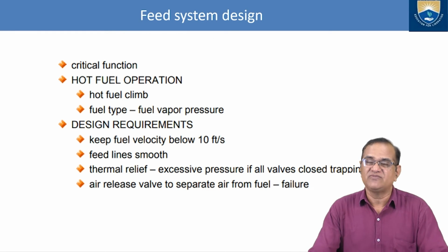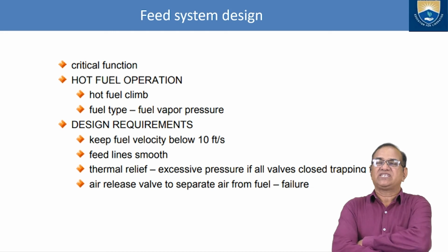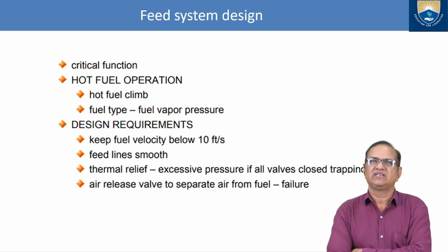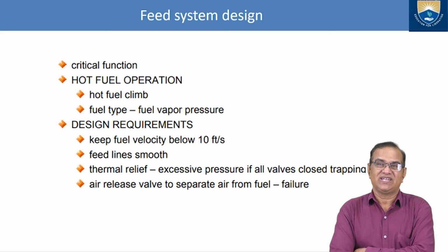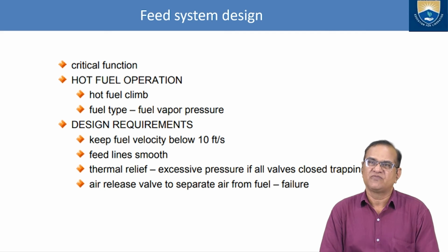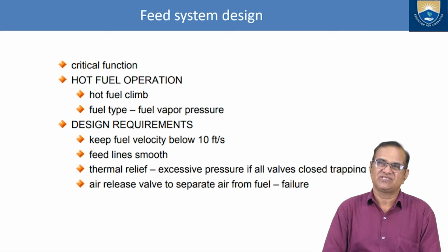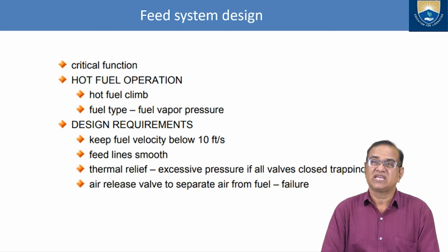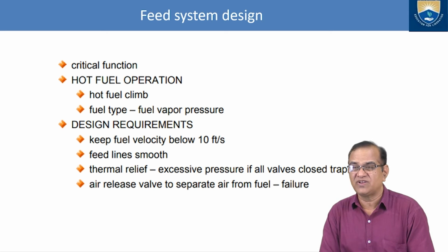Feed system design, if you talk, it is a very critical system to design. Hot fuel operations. Sometimes we need the hot fuel, especially in the cold weather. We have to heat the fuel. Fuel types, fuel vapor pressurized. Design requirement: keep fuel velocity below 10 feet per second.